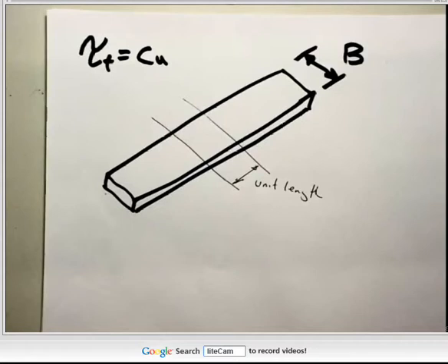So when it's drained, we have to know what the effective stress is locally on the failure surface in order to work out what the shear stress is. But for this particular example, undrained clay, we can estimate it directly from the void ratio, or in a real site investigation, what you'll do is just measure the undrained strength and assume that the void ratio hasn't changed in the period between measurement and construction.